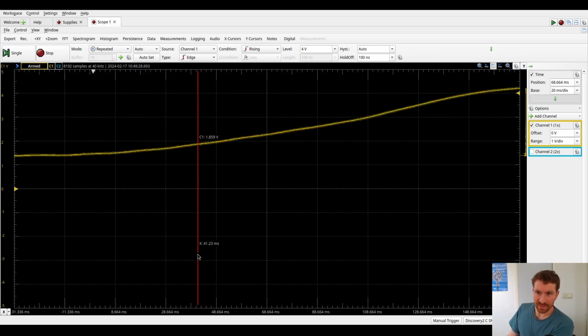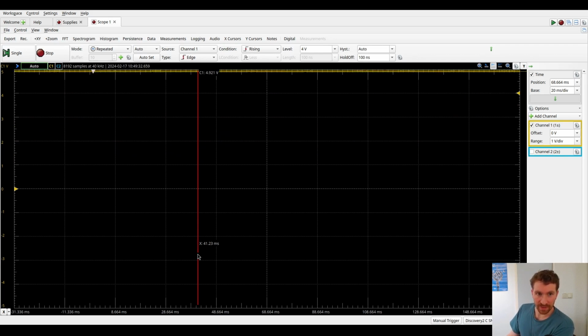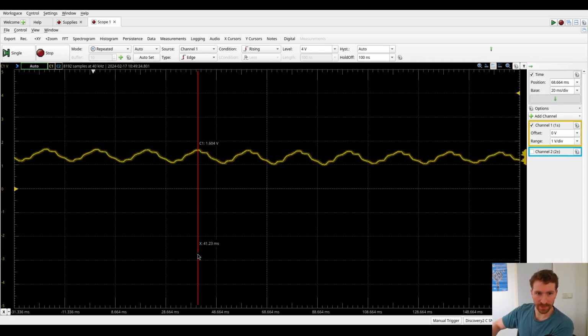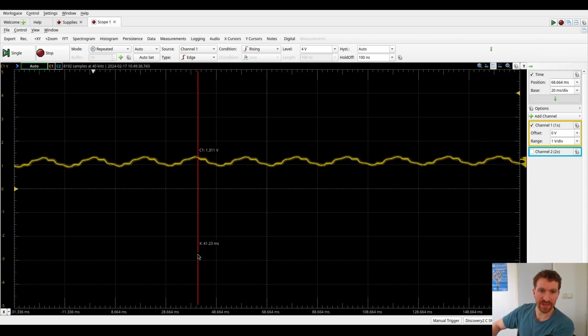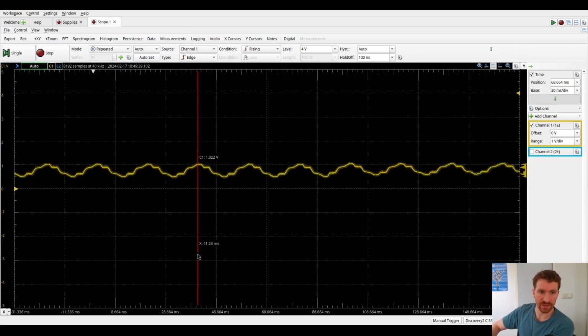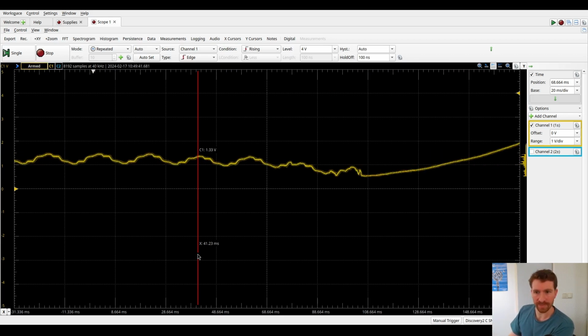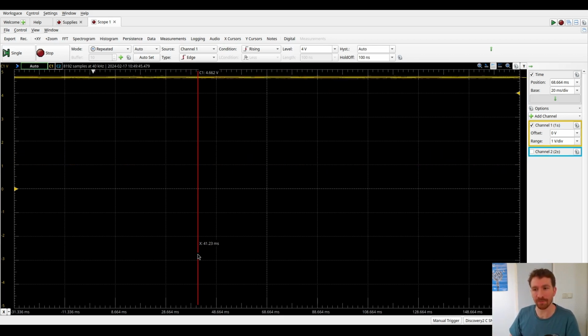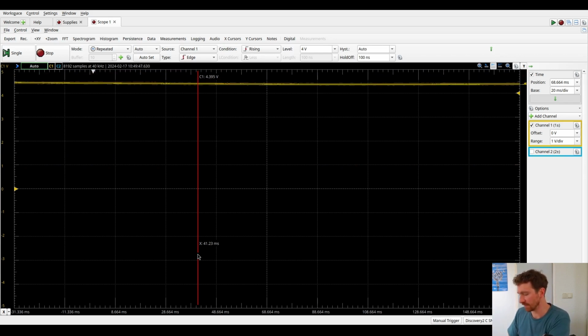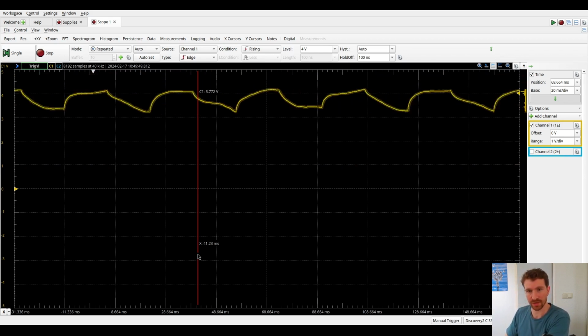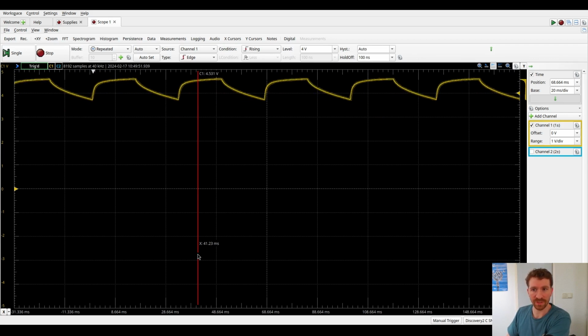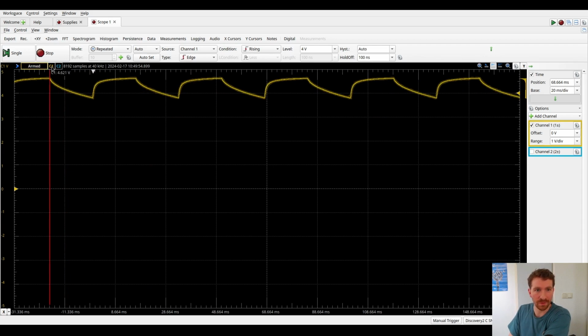So as this thing gets more light, the resistance goes down because we have almost 5 volts on the signal. And as I stick my hand over it and cover the light, the resistance goes up and we get a bigger voltage drop. Okay, so let's see if when we hold this thing over the light, the LED, do we actually get a change? And what you can see here is that we get a very observable signal.